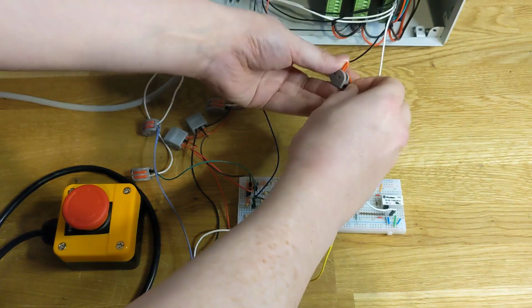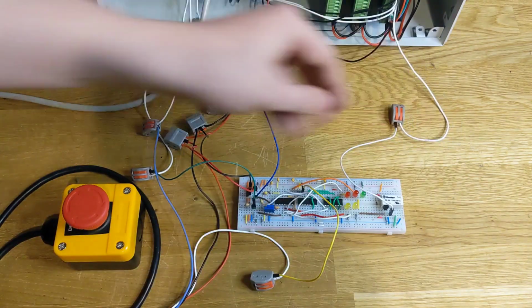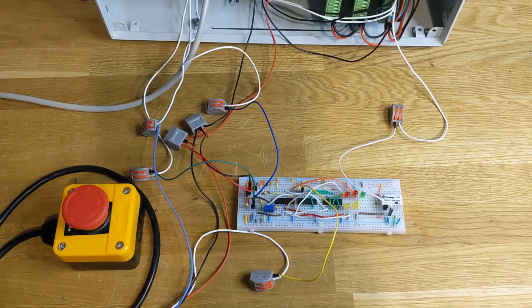The gate output connects to the enable pin on the motor drivers. The way these work is if there is a voltage applied, then the motors are disabled. So we connect the normally closed relay pin to 5 volts, the normally open pin to ground, and the common pin to the motor driver enable positive pin.